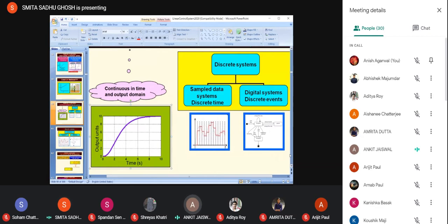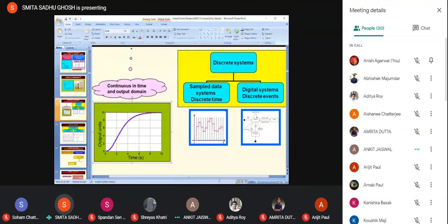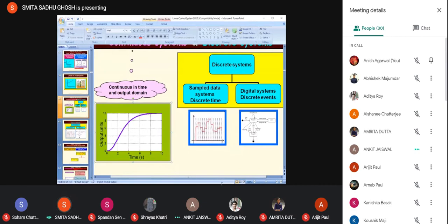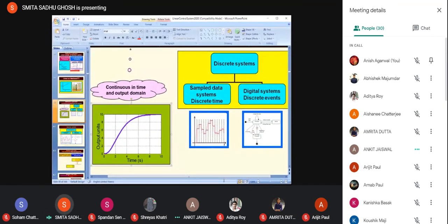Continuous time and discrete time system is defined for input only. If we give continuous time input, then we will get continuous time output. Yes, those things are there. Of course, if you are putting in an impulse, etc., naturally, that might be giving you a discrete output without any reason. That is not our concern right now. What we mean to say is that the system characteristic itself is such that even if you are applying a continuous input, you would get a discrete set of outputs only. In that case, it is a digital system.